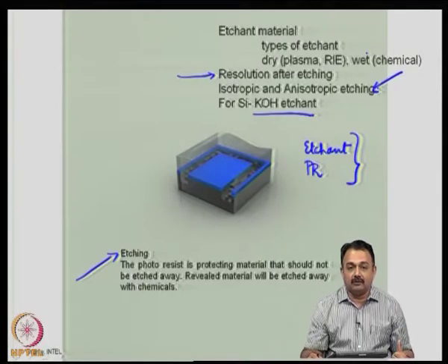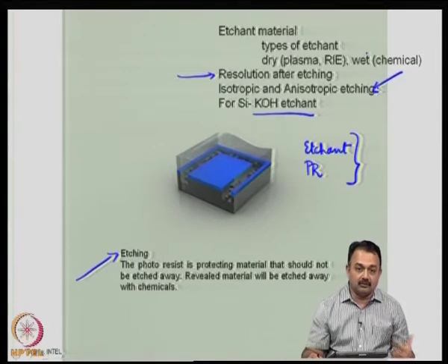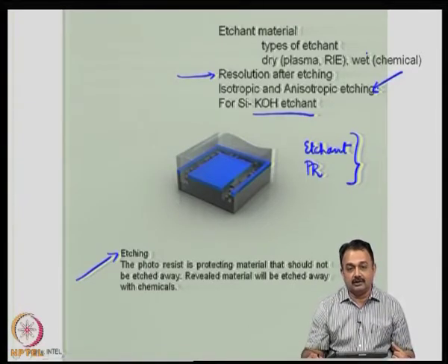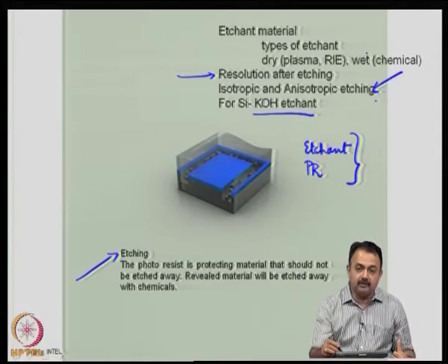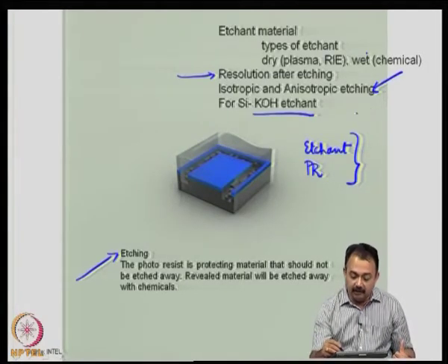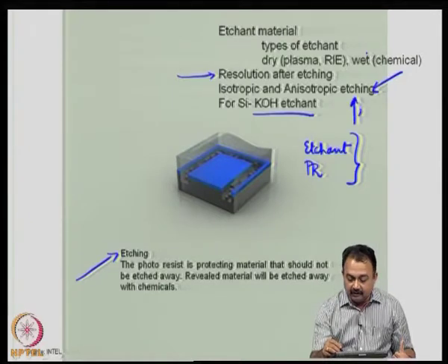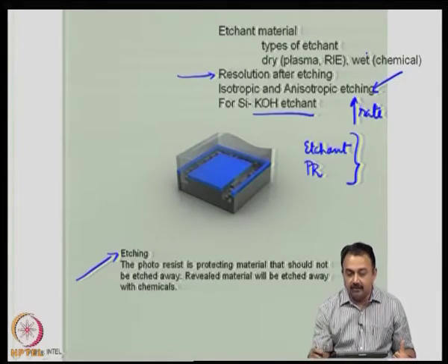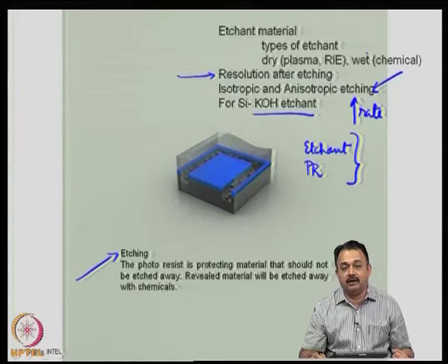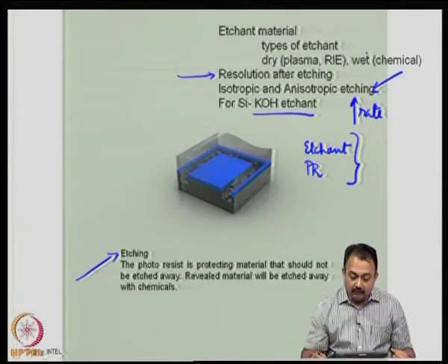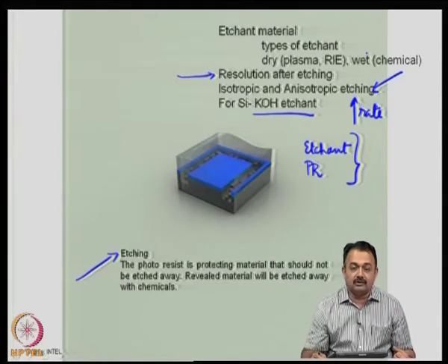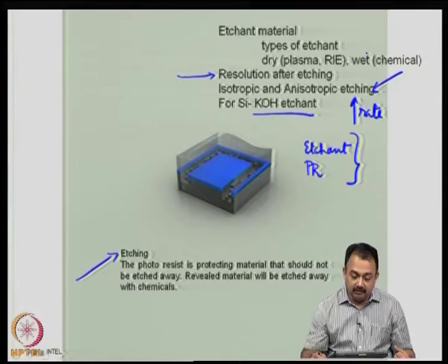In etching also you have a lot of problems, because you can have different types of etching, isotropic etching and anisotropic etching. Some chemicals are isotropic and you can use some etchants that are anisotropic. So, depending upon the thickness that you have and depending upon the rate of etching that you want, you can choose between isotropic and anisotropic etchants. Each will give different types of defects. Okay. So, one has to be very careful to choose the etchant type.